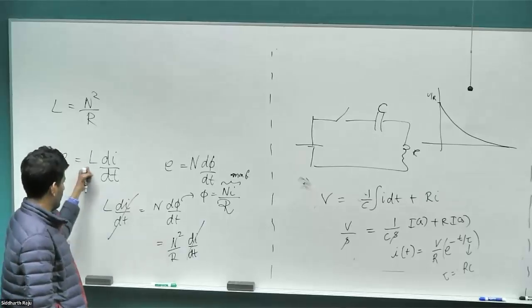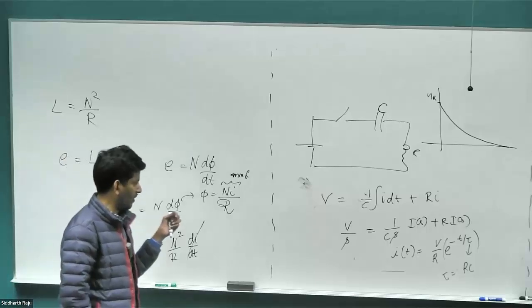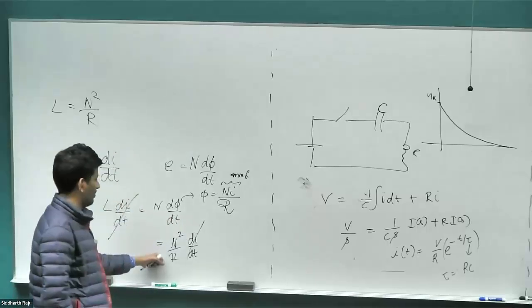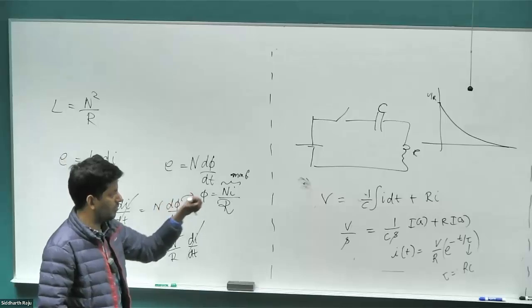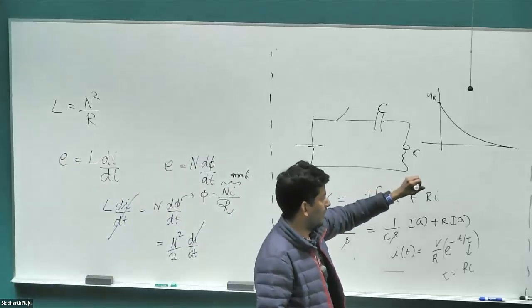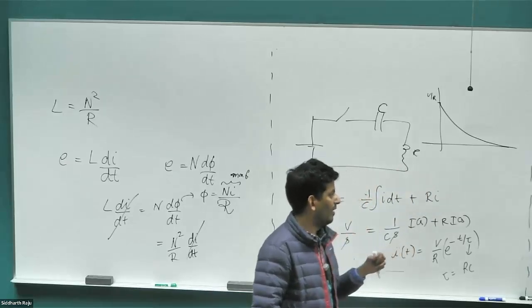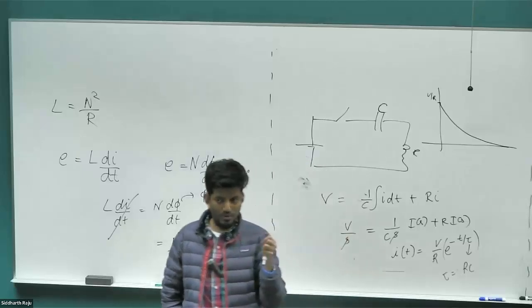Right? So again, if you just remember these two, you'll be able to derive it. But there is a roundabout way of doing it as well. This is for the easy case. But in more complicated networks where the system itself is moving around, let's say a small segment in the magnetic circuit is moving back and forth, and you want to find out the variable inductance, in which case, what will you do? What is the other way of figuring out the same thing?